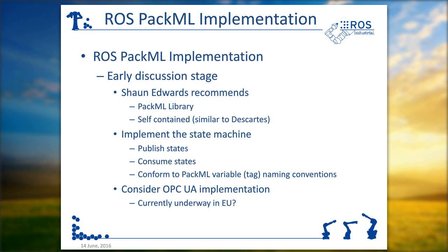Also, this OPC UA implementation, I really want to. Let's see. Somebody said something about ROS projects having a compatibility guide with MTConnect. Okay, so we'll talk about that because we're going to need that. A standard OPC implementation would be better in the U.S. because it's such an entrenched standard here, but it's terrible. Having DCOM and working with all of the things that you have to do with it is a nightmare. So we're trying to switch people over here to UA, but it's slow going.